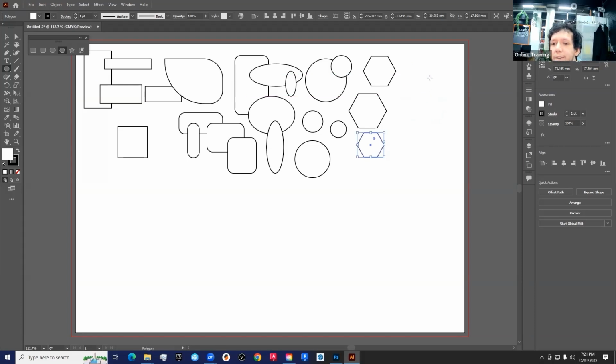Oh, so it's once I've started drawing the shape, so I'm clicking and dragging to draw the shape, and then before I let go of the mouse button. If I've already drawn a shape and I want to change the number of sides it has, on the right hand side of its bounding box, the bounding box being the containing box that allows me to control it, you'll see that there's a little diamond, and as I hover the mouse over that, I get a little plus and minus, and if I drag that diamond up or down, I can change the number of sides, but only up to 11 sides.